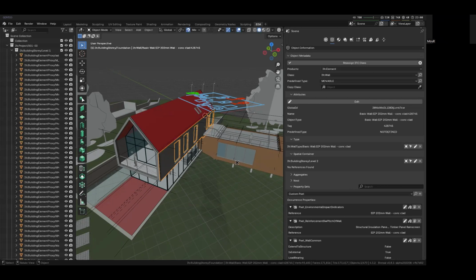If you are doing things like clash detection, go and standardize your clash priorities and clash set rules in terms of IFC classes. If you're doing naming schemes, create your naming schemes based on IFC classes. So there's lots and lots of things you can connect it to, and it's really quite an easy classification system to learn. I've learned quite a few classification systems. I would say maybe things like the Revit categories, because Revit categories are a classification system in themselves. That's also really easy to learn because it's so little. It's also pretty much 1 level deep. I know Revit sort of has subcategories, but it's really only 1 level deep. So it's really easy to learn.